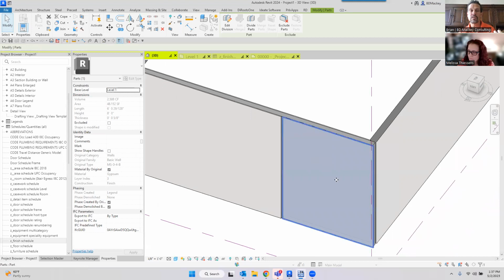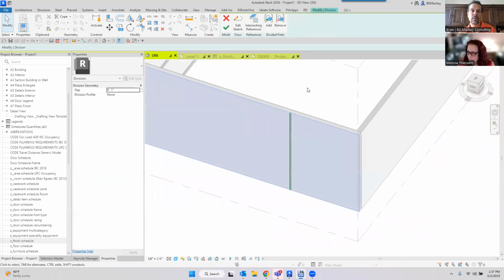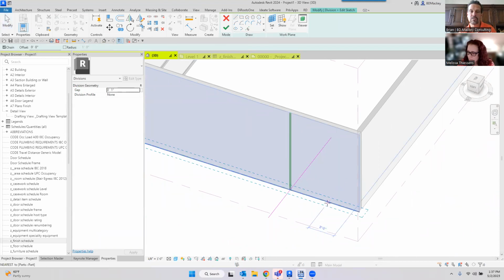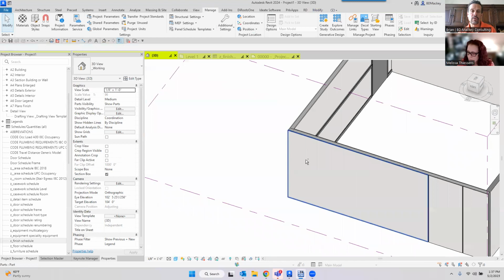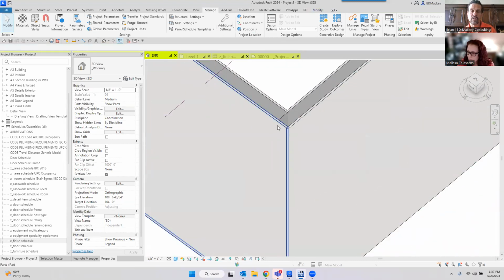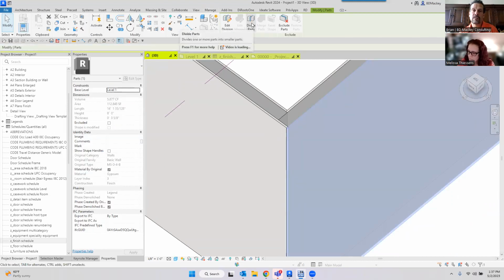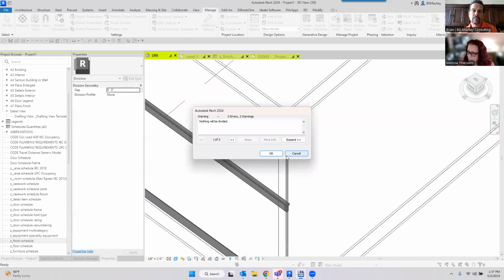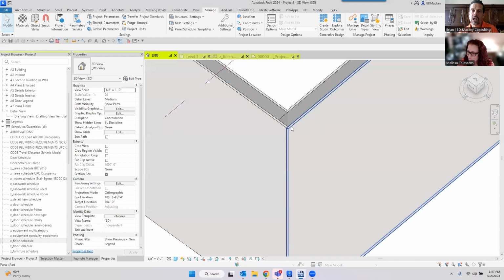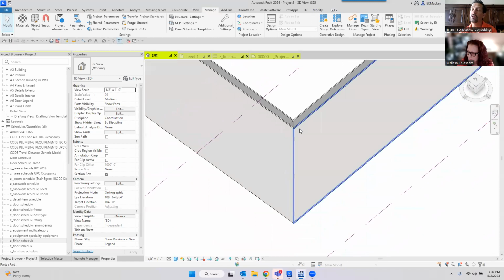So now you can see, ooh, here's this part. Then I could go edit the division of this part. I could go edit the sketch. I think I could change the work plane if I needed to go vertical, but you get the point here. I could finish that out and then have another division. So you can start subdividing, dividing, or even around the corner like this here. Maybe you wanted this to be represented as a single part. So if I grab this one, I can say divide parts. I can add this part to it, finish, and now it's not going to let me divide it. But a lot of times for like concrete buildings around the corner, then we can start merging these parts together and get them to do what they needed to do.